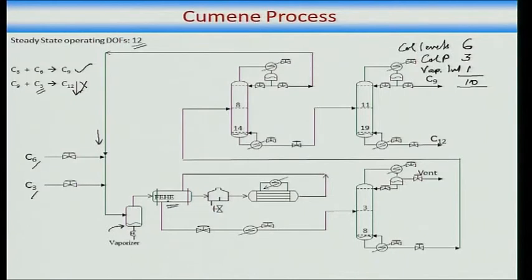What does the feed effluent heat exchanger do? It takes the hot reactor effluent, and that hot reactor effluent is used to preheat the cold feed to the reactor. Then you have a furnace that heats the feed to the desired reactor temperature, and actually the reaction temperature is quite high, 320 to 330 degrees Celsius. The reactor is a shell and tube heat exchanger with catalyst loaded tubes, and it is cooled by circulating coolant at a very high rate on the shell side. So, what that means is that the shell side temperature is essentially constant. Okay. This is what is being shown here.